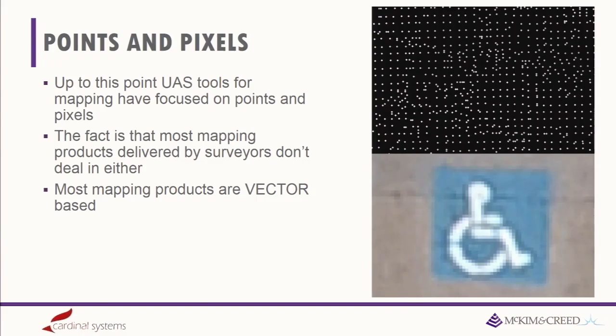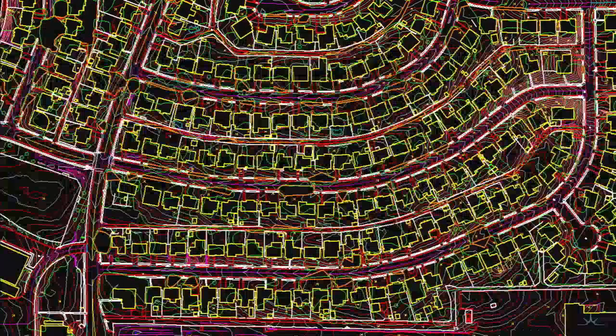But in the survey world, this is what we deal with mostly. Not to say we don't use orthos, we don't use point clouds, but when it gets down to it, we want to end up with some kind of vector feature. We want something we can apply topological rules to, attributes, levels, line styles, etc. And that's one of the limitations right now, to get all this information accurately, the edges of buildings, the curbs and gutters. The image-derived point cloud method doesn't work, and doing it with ortho for buildings, there can be lean and other things cause horizontal error, and elevations can be incorrect.